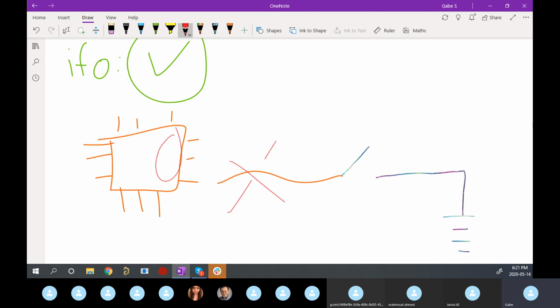What's the state of the pin? You don't know. You don't know what that pin is going to float to. You don't know if it's going to, due to the noise all around it, float up to 3v3. You don't know if it's going to float down to 0 volts. And so you could be tricked, right?